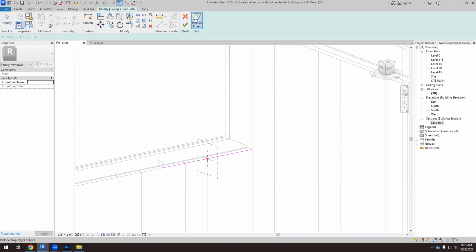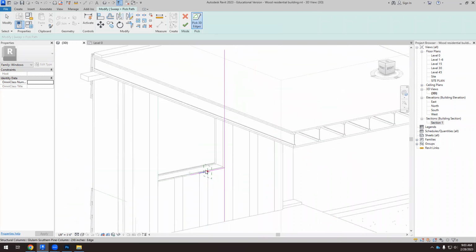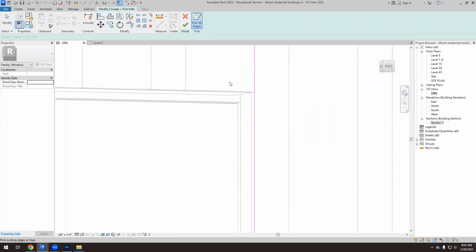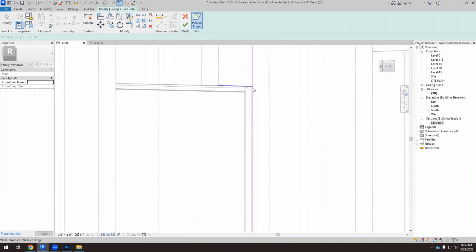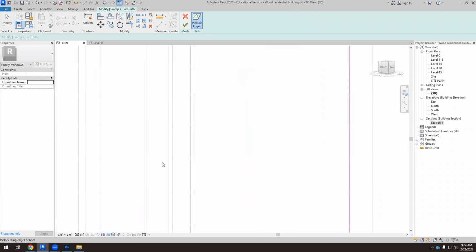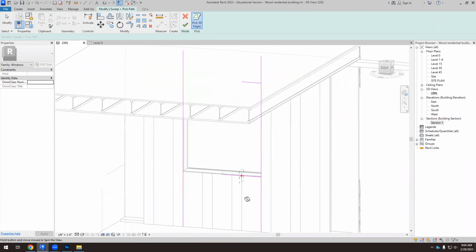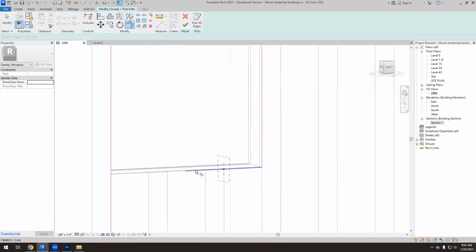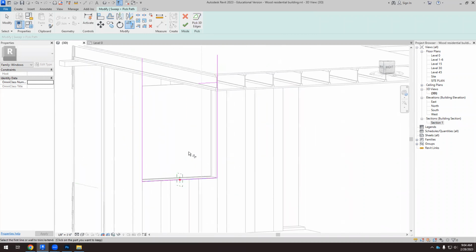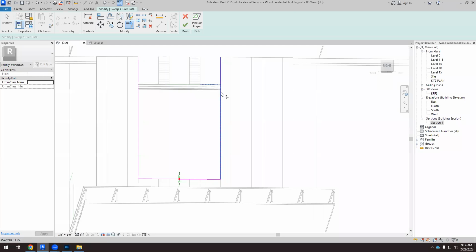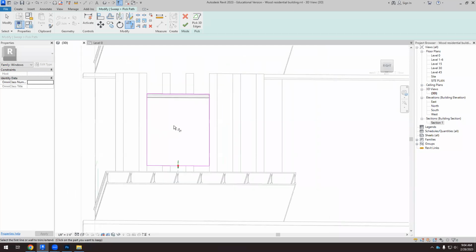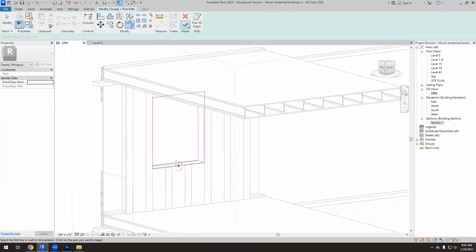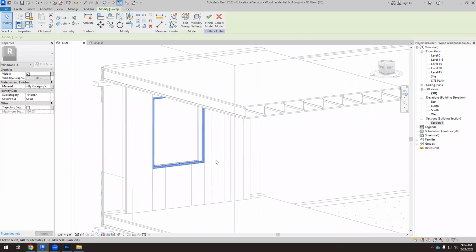And by clicking pick 3D edges, now I have to select this element here, another one here, and now I have to trim. If I trim this and this, this and that, and here, this and this, and this and that, now I think it will work. Yes.